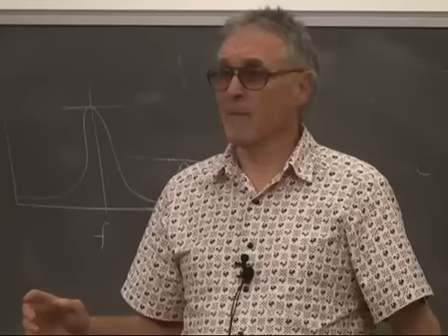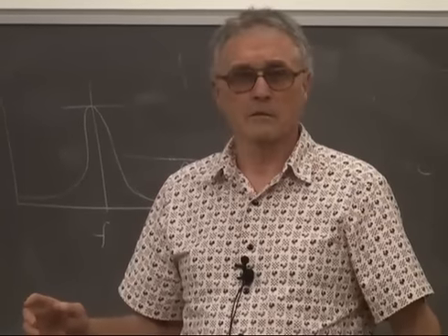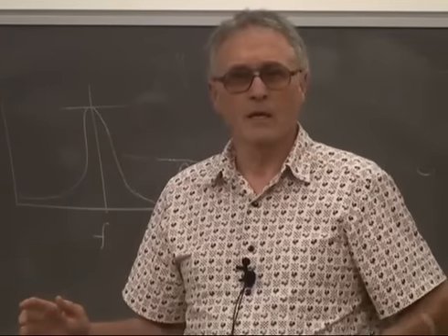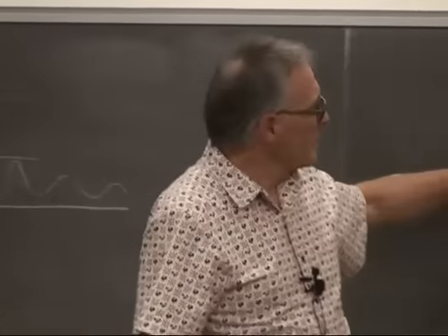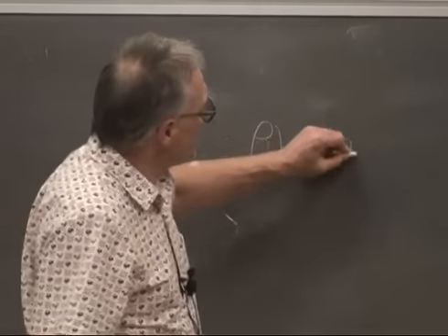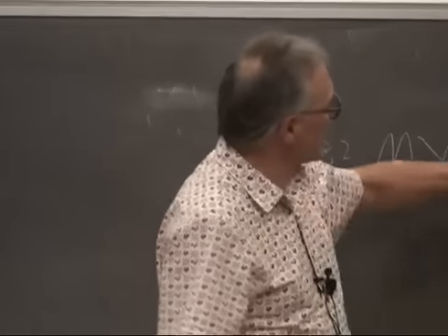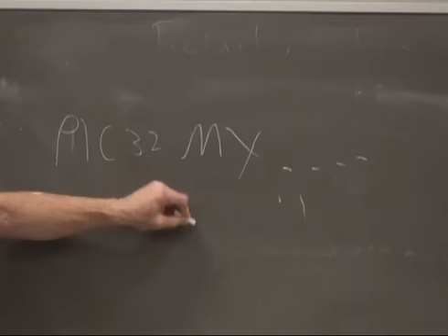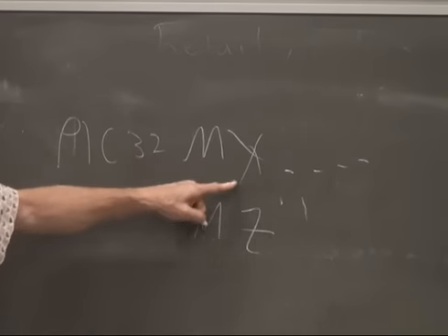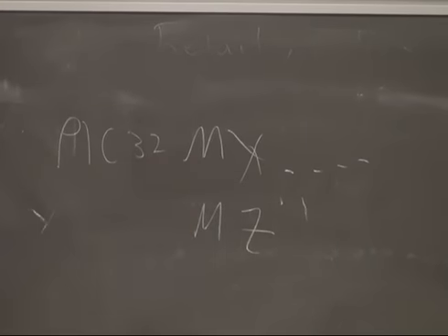And it's got to be an MX, not a... what's the other one? There's the PIC32 MZ, that's right. You can use any of the MX versions you want. The MZ is quite a different architecture. Don't do it.